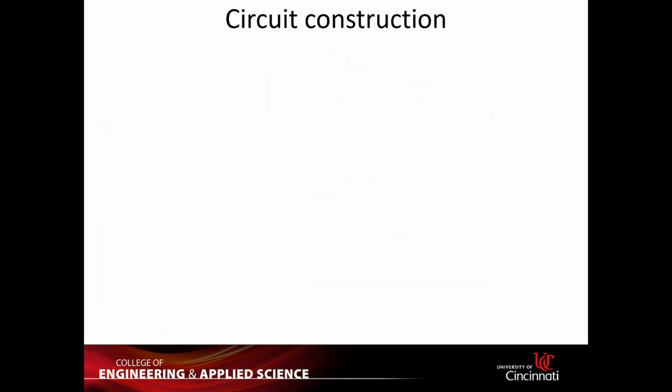Finally, we started with the circuit, right? We have all of the elements, but actually, if you remember, we have the state table, right? So from the state table, we can have the state diagram. State table, state diagram, that one you can go back and forth. Then from those elements, you can make the D flip-flop input equations.